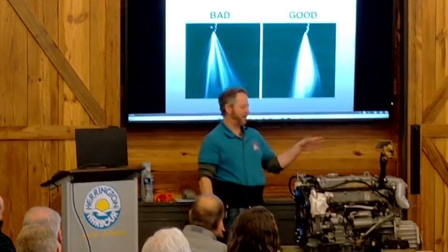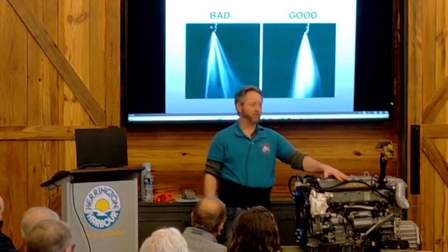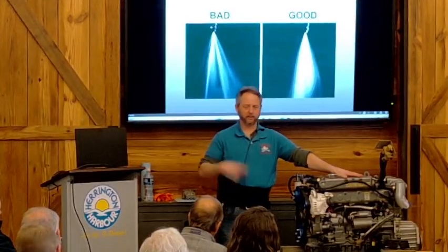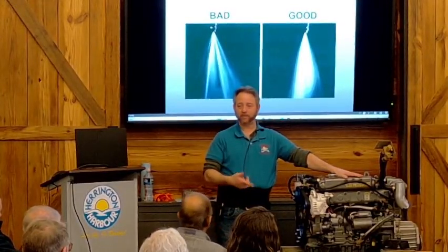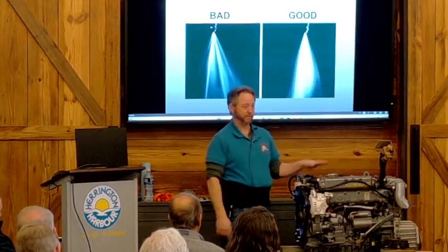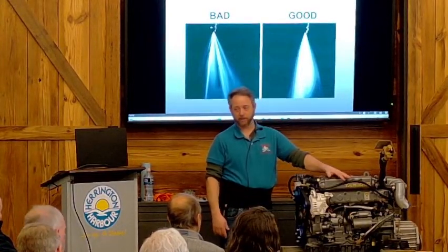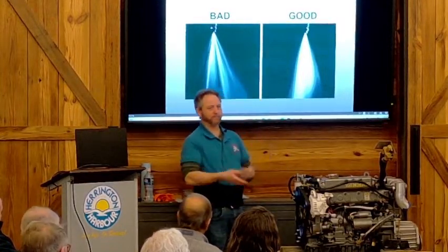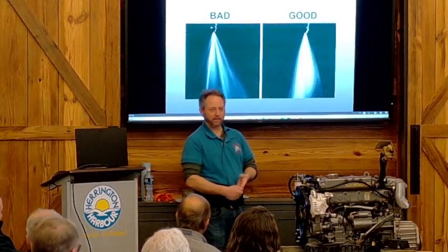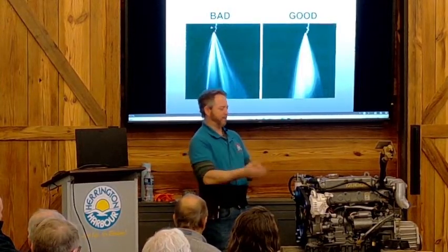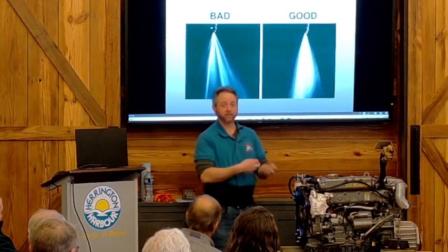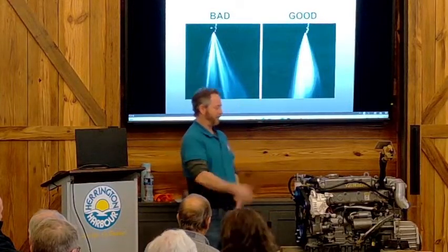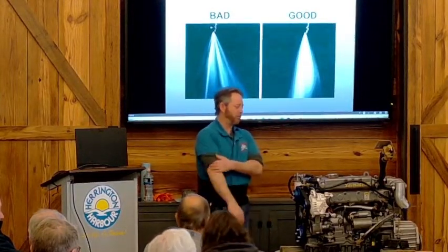At winterization time, you test your coolant for freeze protection, and this coolant is on a maintenance schedule to be replaced every 2 to 3 years, which a lot of people don't do, because antifreeze will break down just from sitting and being used, and it won't have the correct properties to exchange the heat. So we want to make sure we have a good mixture of distilled water and coolant in the engine.